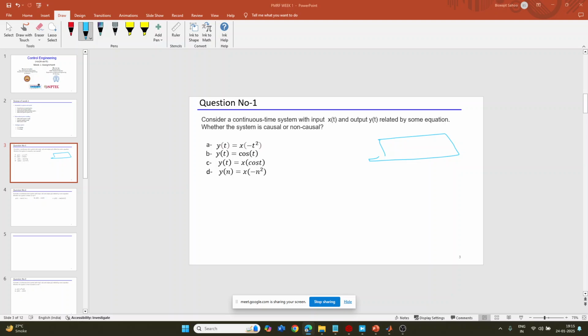Designing the charger means working with power electronics, or RLC components; some are linear components and some are non-linear. Now you have to select a topology. Let's say a buck converter, a simple RLC network. You have to find the relation to your output voltage. Let's say I'm going to charge a 48-volt battery, while somebody else wants to charge a 400-volt battery. The system requirement is different, so whatever is inside the charger is also different.